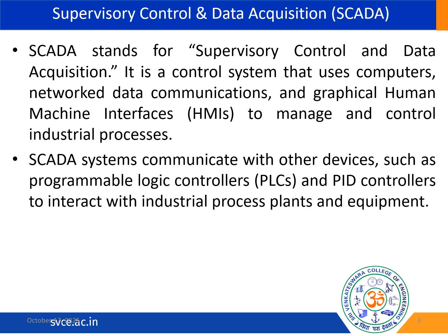There should be no leakage along the pipeline. If any leakage occurs, the SCADA system is used to identify it. It infers the information, transmits it to the system, displays it on the computer screen, and gives the operator an alert. So we can consider this as an example.